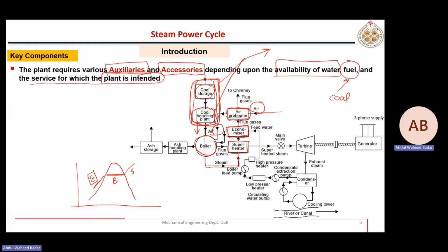And you see here, these exhaust gases, after combustion, first go into the superheater. So they transfer their energy to this fluid, which is at the highest temperature. Superheater is this part. And then they go to the boiler. That is not shown here properly. We will see when we'll be discussing boiler separately, in a separate chapter on boiler. So first, these combustion gases go into the superheater, then to the boiler, and then to the economizer here.